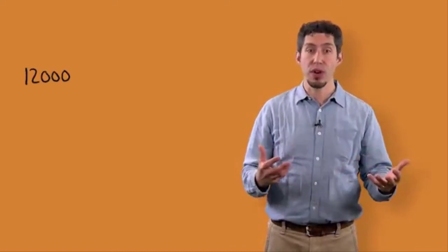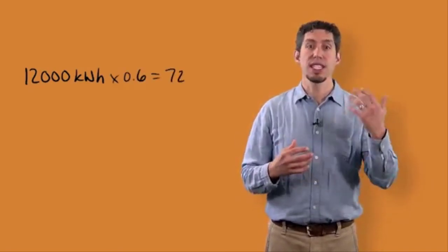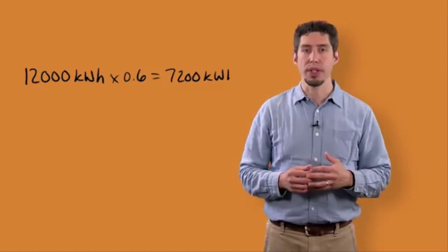So there's an alternative option if maybe we can't afford those 37 panels or can't replace 100% of the load, but maybe we can replace 60% of the load. In this case, 60% of 12,000 is 7,200 kilowatt hours per year.